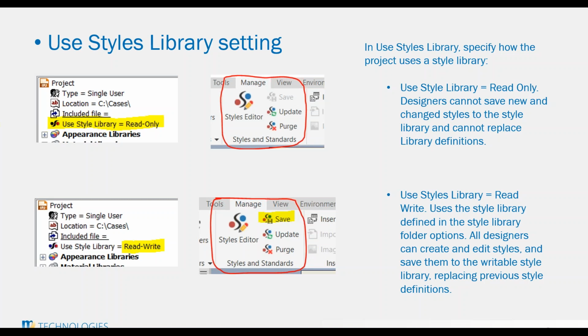They can make that change to the drawing only. Normally, that information needs to be pushed back to the design data folder, and the XML needs to be written back to the master location. If you have the read-only setting, you are telling the users any design data change that they make is only going to be made for that specific document.